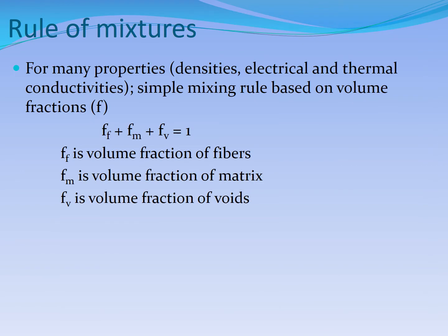Let us go. Rule of mixtures. The most important equation or theory or whatever you say in composites. For many properties, density, electrical conductivity, thermal conductivity of the composite, we use the rule of mixtures. Simple mixing rule based on volume fractions.